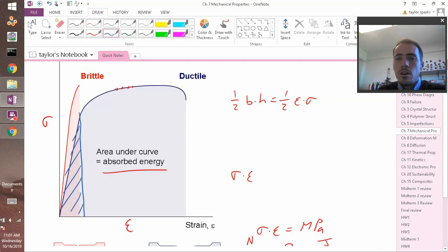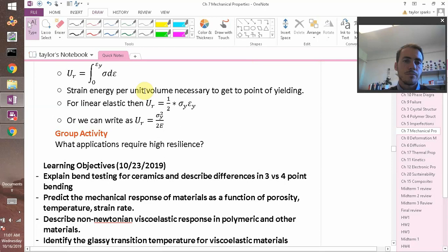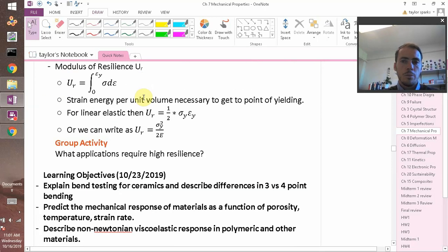That's a useful thing, like springs. For springs, you want a spring to be able to go back and forth like this. You want lots of energy maybe if you want a stiff rubber band, but you don't want it to deform, so you want a high resilience. So that's the difference between toughness, which is the total area, meaning this is all permanently deformed in this region, versus resilience, which is just elastic deformation, not plastic deformation. Okay, and we'll pick up here next class.